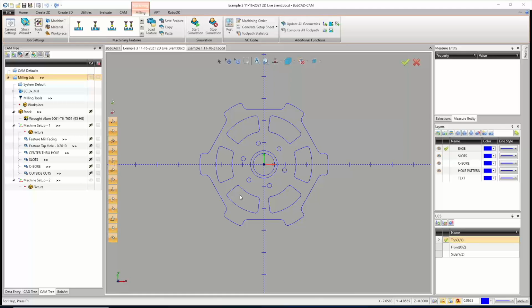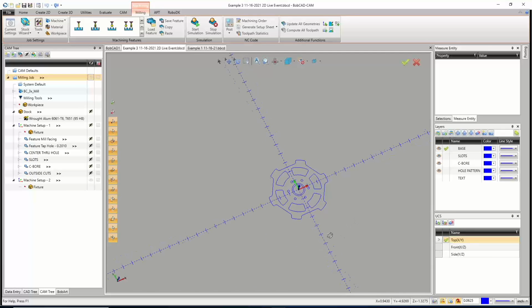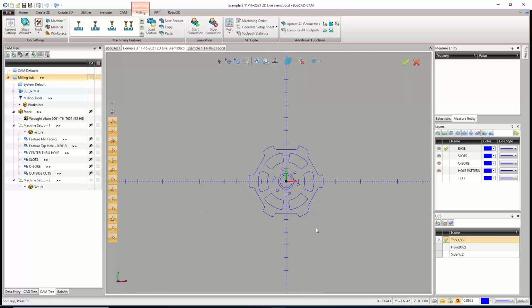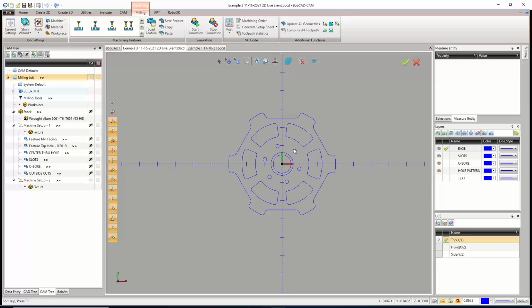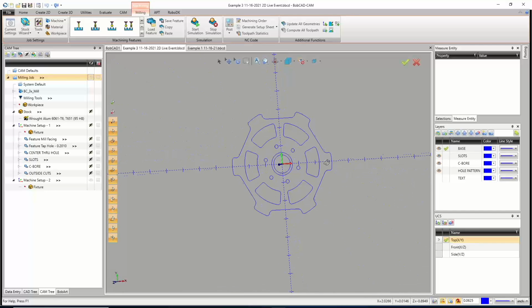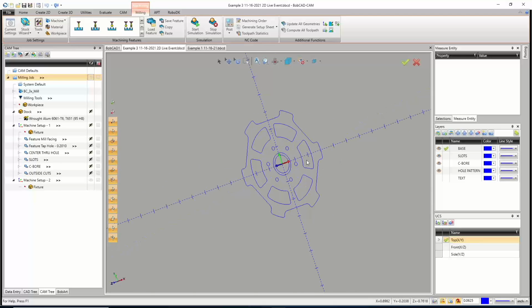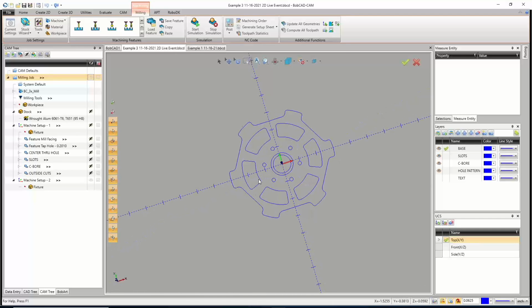But we have to make sure, especially if we needed to drill the holes in that specific location, that when we flip our part over, we flip it the same way at the machine later on, especially with that hole pattern being off. Because if I rotate across the y-axis, the hole switches spots. So it's just knowing which way you did it. Really, it's not that important.